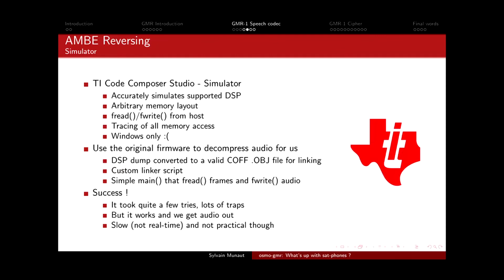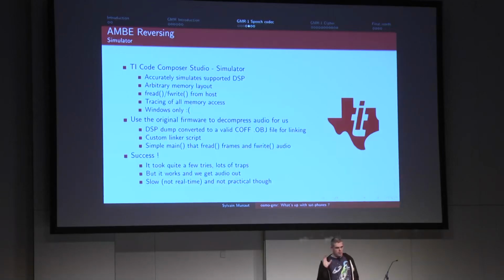So before trying to actually reverse engineer, we just tried, okay, maybe we can just run it. It turns out that TI has this really nice program called TI Code Composer Studio, which includes a simulator. And it's a really nice piece of software because not only can you pretty accurately simulate any of the DSPs, you can also completely configure the surrounding environment in which it runs.